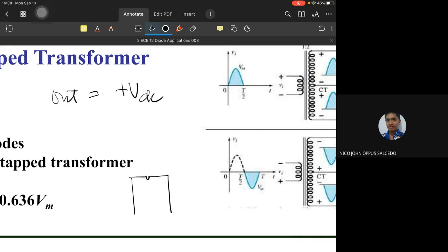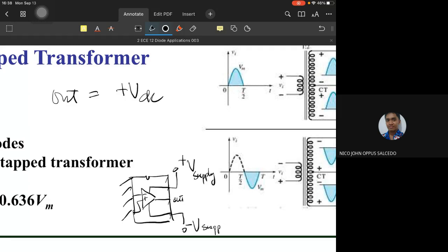an IC chip. And this chip is an integrated circuit for an operational amplifier. An operational amplifier needs a positive supply and a negative supply. And most chips are like this, right? So it needs a positive supply and a negative supply, let's say for example positive 5 and negative 5 volts.